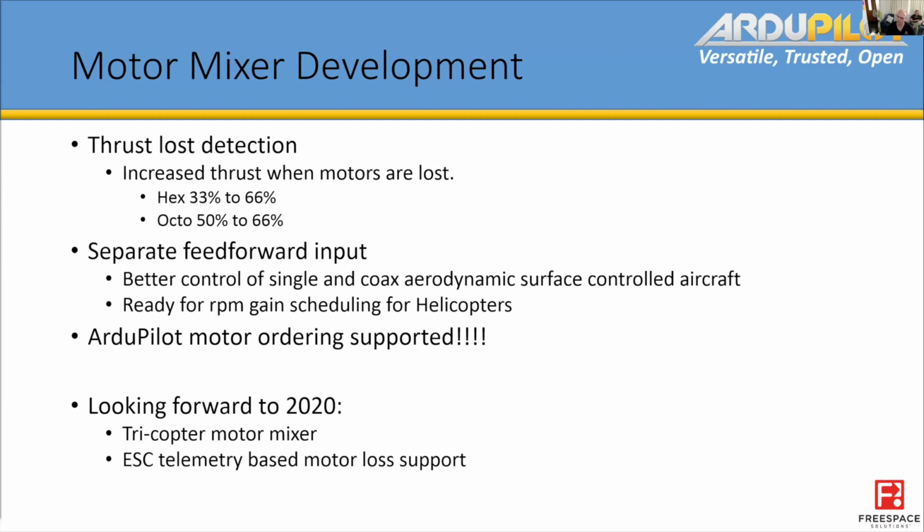That's an absolute godsend, to finally have our own motor ordering that actually matches the propeller test and actually makes sense. We've been dealing with a hangover of what somebody did right back on the first implementation, when I was first trying to get these things to hover, and been stuck with it ever since. So I'm looking forward to slowly changing all my aircraft over to that and actually having the servo output, ESC output order matching my propeller order.